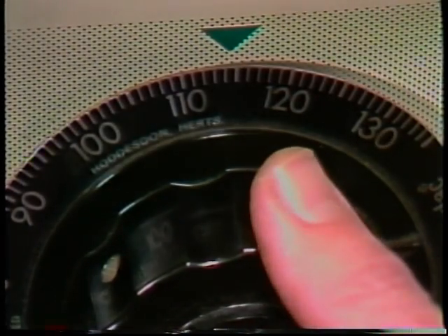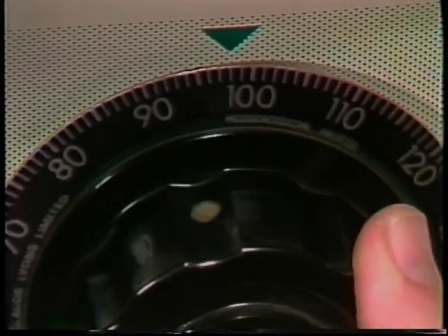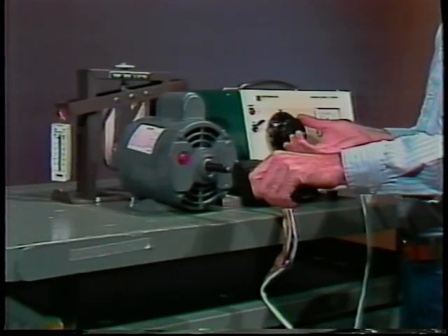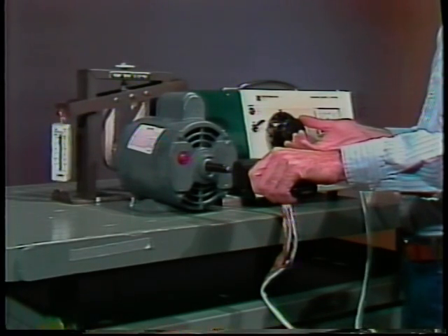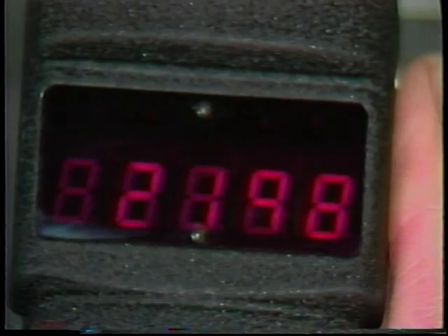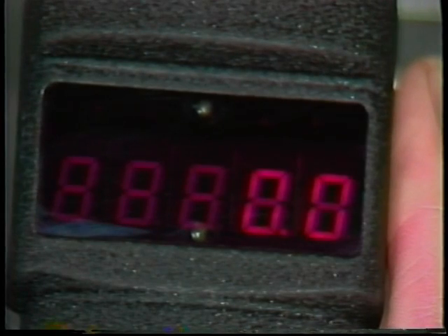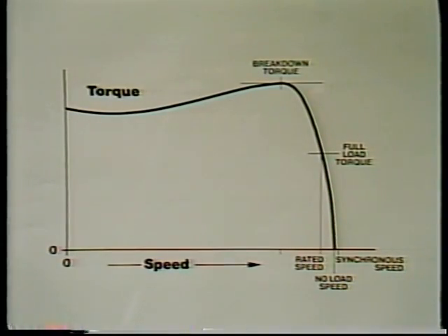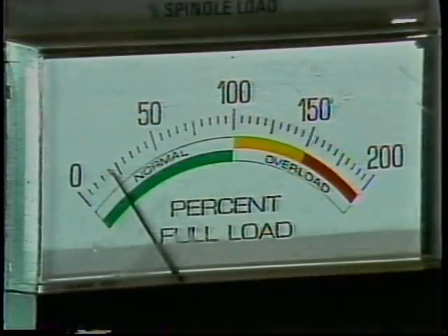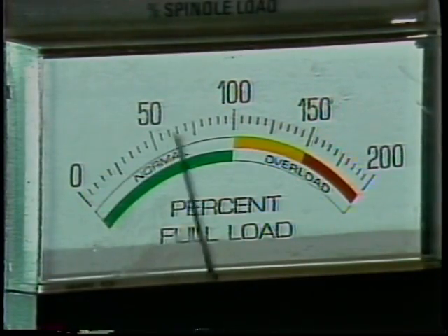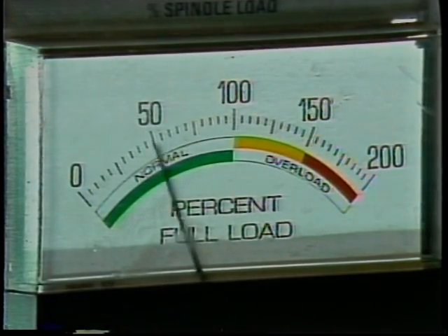Induction motors are especially likely to stall if line voltage is a little low. A line voltage drop of only 20% can reduce breakdown torque so much that the motor will stall even with its normal load. When the motor is stalled, it exerts the same amount of torque that it exerts trying to start its load. On almost all motors, startup torque is greater than full load torque.